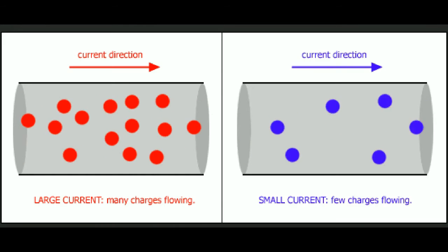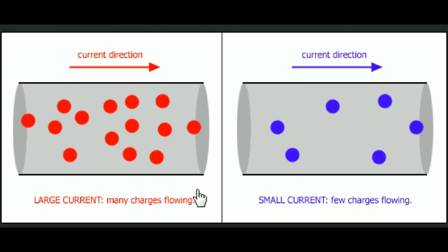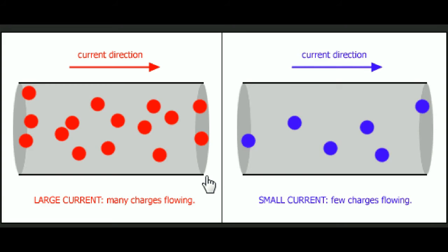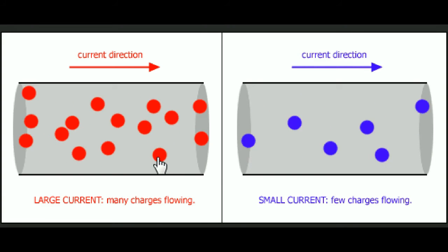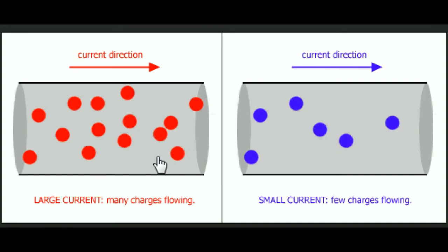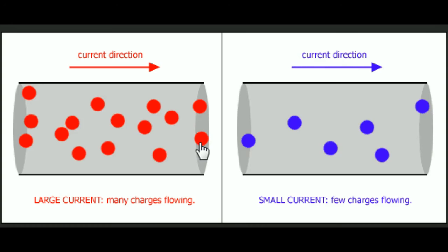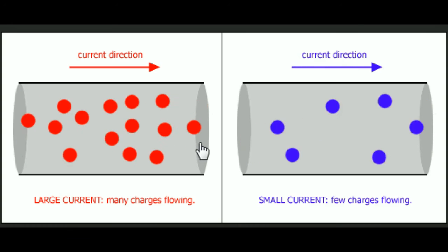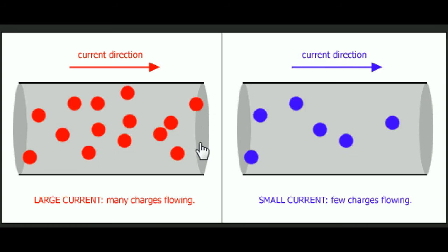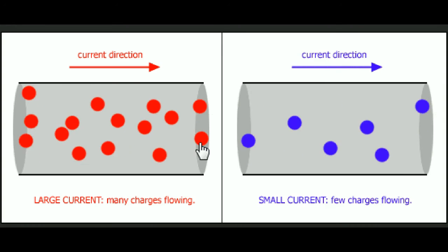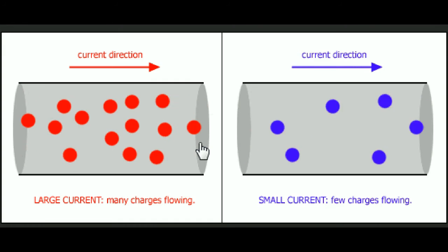In this animation, we see the difference between a large and a small current flowing through a conductor with a given area. And what's interesting to note here, and it's obvious that this is a larger current flow, which would represent the movement of electrons, is if you watch right here exiting the wire, occasionally you'll see one electron and occasionally two. And that random flow of electrons actually produces a type of noise in a circuit. It's called random arrival.